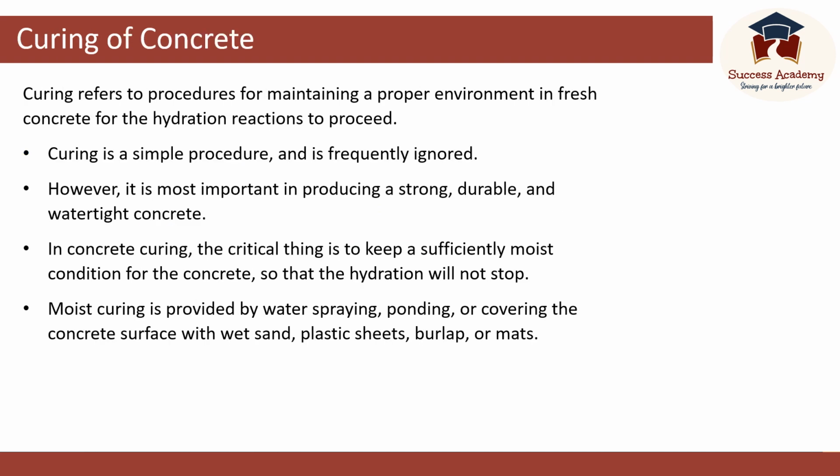Curing is an important step in concrete construction. Curing refers to procedures for maintaining a proper environment in fresh concrete for the hydration reaction to proceed. Curing is a simple procedure, but it is frequently ignored. However, it is most important in producing a strong, durable and watertight concrete. In concrete curing, the critical thing is to keep sufficient moisture in the concrete so that the hydration will not stop halfway.